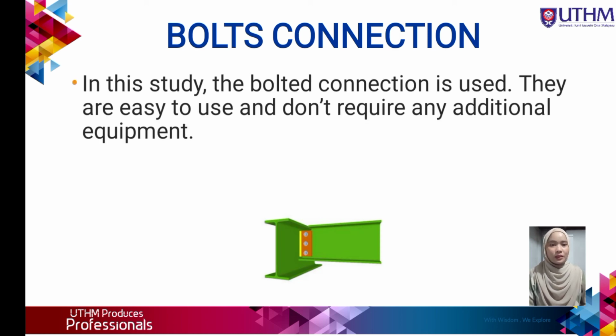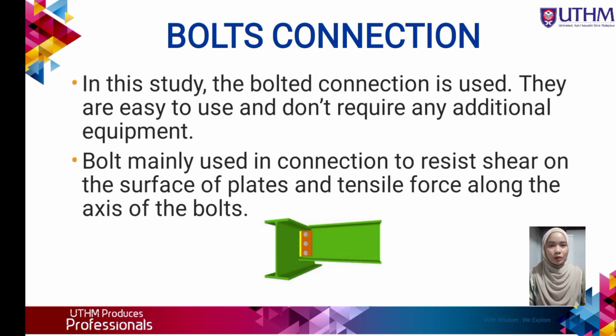Today I would like to talk about the design of connections. In this study, we have chosen bolted connections in our design. The reason we use bolted connections is because they are easy to use and do not require any additional equipment. Bolts are mainly used in connections to resist shear on the surface of plates and tensile force along the axis of the bolt.